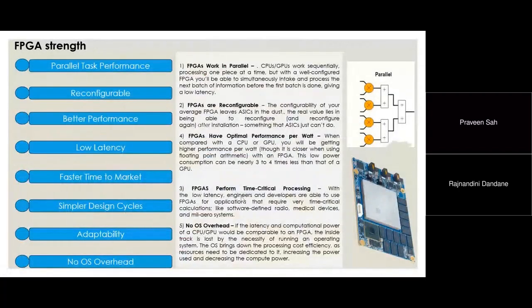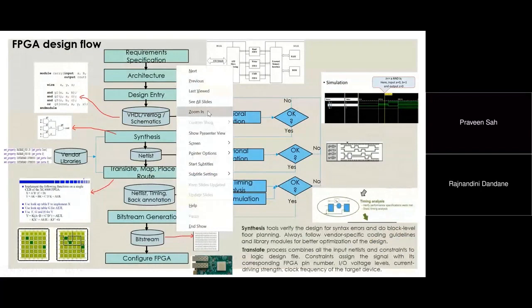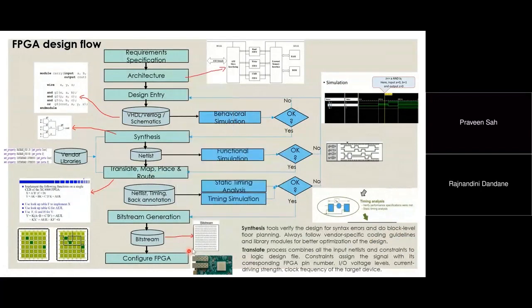That is the last file we get, which we flash into the firmware, the .mcs file. Whenever you want to program, let's suppose I have this hardware and you are writing the configuration file, I will just ask, Nandini, can you give me the .mcs file? That is enough for me. I will flash that .mcs file onto the FPGA and it will start working as per the requirement. So .mcs is the last file for Xilinx, but for other vendors like Intel and Altera it is a different format, though it is nothing but a bitstream.